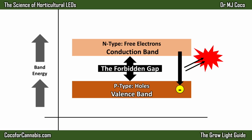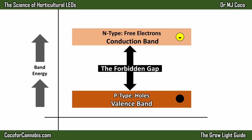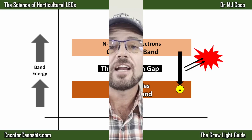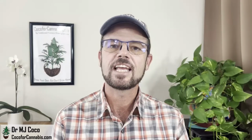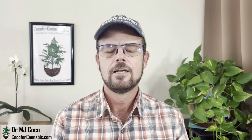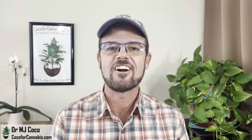Whatever the case, each semiconductor produces a single wavelength of photons, in other words, monochromatic light. A 450 nanometer diode uses a semiconductor that creates 450 nanometer photons, and a 660 nanometer diode uses a semiconductor that creates 660 nanometer photons. There are now semiconductors that create a huge range of specific wavelengths, but each semiconductor can only create one wavelength. They all create monochromatic light. A semiconductor cannot make full spectrum or white light. Of course, we now have full spectrum white diodes, but before I consider them, let's consider our next question.